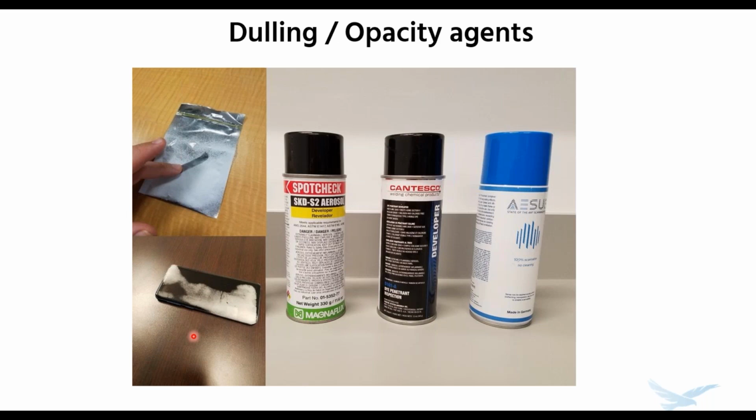So yeah, shininess and capturing thin edges and stuff is something we'll dive into a lot more on the 21st, but that's the gist of it, is that you need a very high resolution scanner to capture thin edges, and lasers are going to work better for capturing thin edges. There are some tips and tricks that we'll go over for capturing thin edges with other technologies like structured light. A simple one would just be throw some masking tape on the edge, and there's your edge location. Double up a piece of tape and subtract half of that with your calipers.